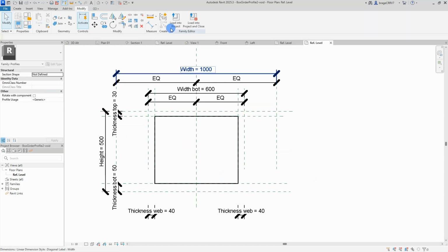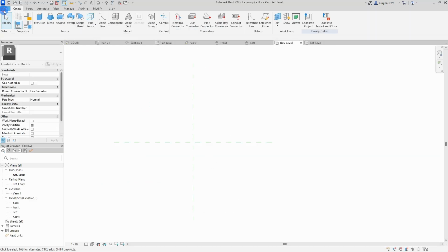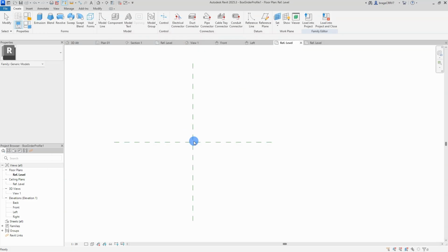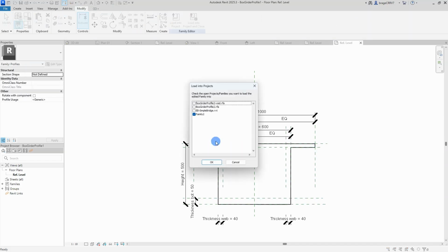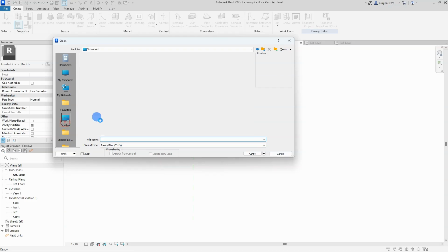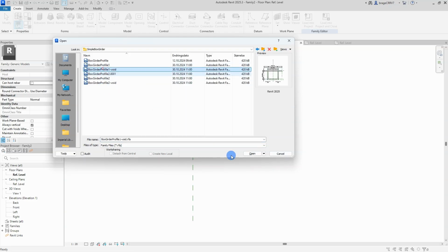Nesting in Revit allows us to place families within other families in order to display their combined geometries and make them behave like a single unit within a project. There are many use cases for nesting Revit content, such as the use of repeated components or parametric elements in an array.